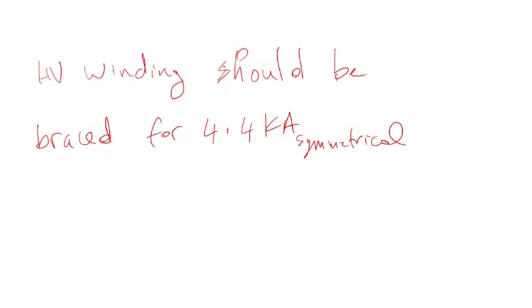But the high voltage winding has to be designed at least to carry this current, but then you have to calculate the three-phase fault and also the three-phase short circuit fault, then the line-to-line fault and line-to-line to ground fault, and the highest of those should decide what the high voltage winding needs to be designed for.